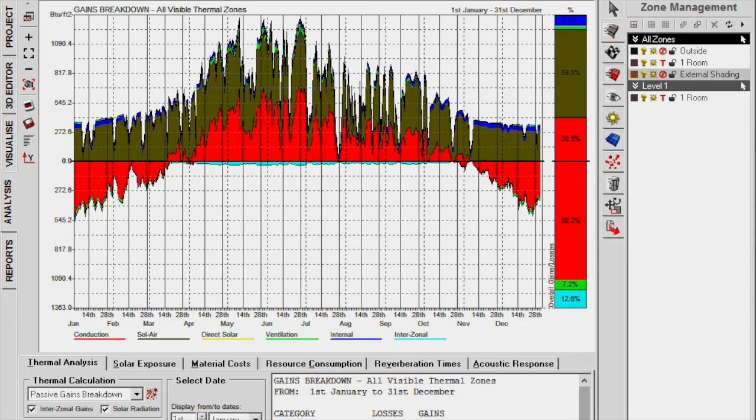Okay, so this is the R value. That's the U value. And the way these are actually expressed is, in different unit systems, in the English system, these are BTUs. I think it's per square foot, but it might be per square inch per hour. So what's this a measure of? That's basically for every square foot of wall that we cut out there, how much heat's going to flow through that wall every hour.